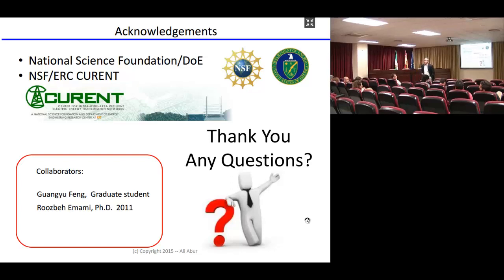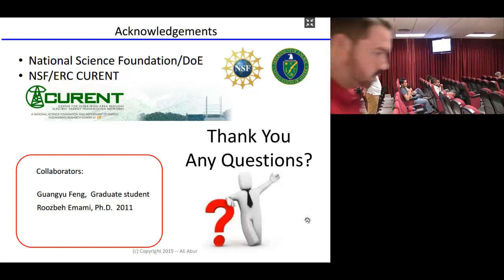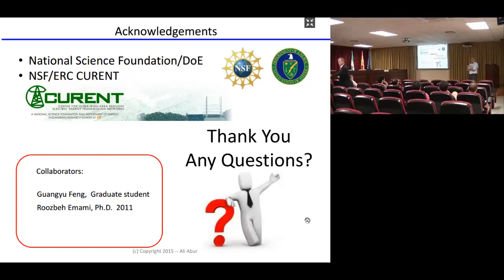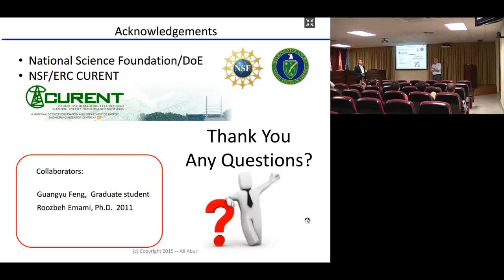Hello. You were talking about internal and external systems, and I want to know what is the interest for an internal system to know what line was taken out? Yes, I think that's a good question. Mainly, as you know, the way systems operate, the control centers run the so-called contingency analysis on a regular basis. So at each point in time, you have to look ahead about an hour and look at how these things, loads and so forth, are changing. And then you go through power flow solutions corresponding to a bunch of contingencies like line outages, generation losses, and so forth. And make sure that under those contingencies, your system remains safe, secure.